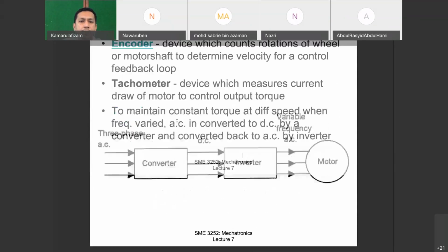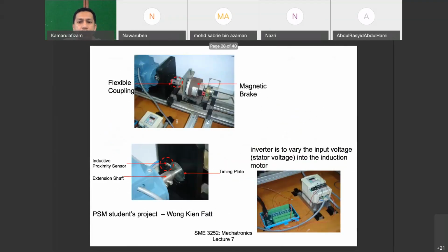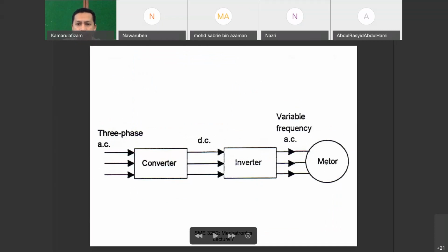Control method biasanya inverter. Okay, because the AC you need to use some kind of inverter, and this is inverter punya bentuk lah. Okay, because motor AC you need some kind of voltage response dekat 3 line ni untuk control motor punya operation, because this is, I would say, a 3-phase punya motor. Inverter ni kena play around dengan fasa setiap sinusoid kat sini to make sure the motor run smoothly. So you need inverter to run AC motor.